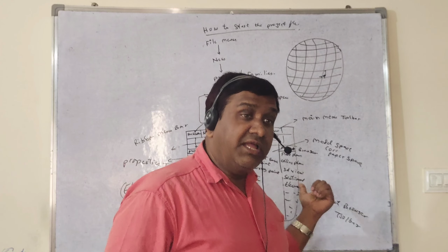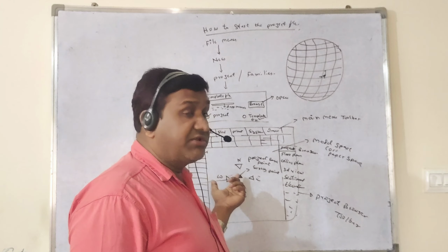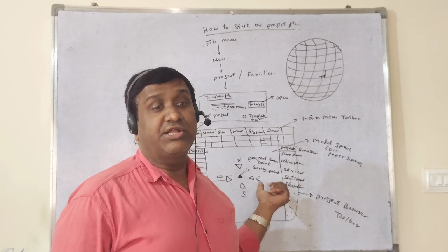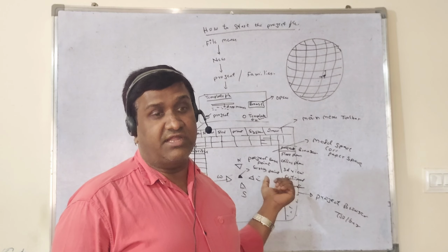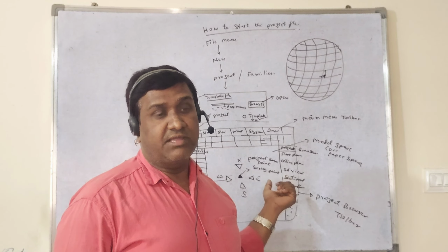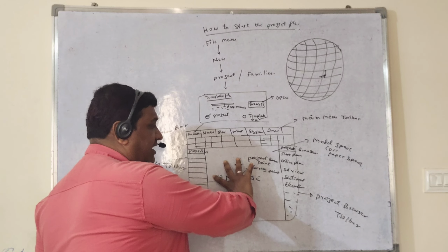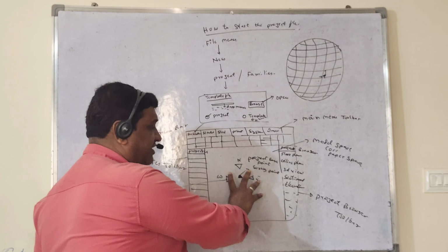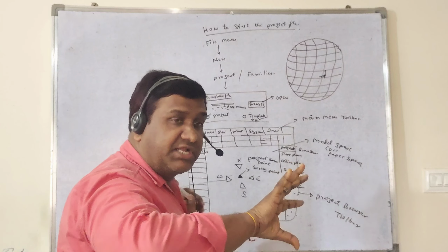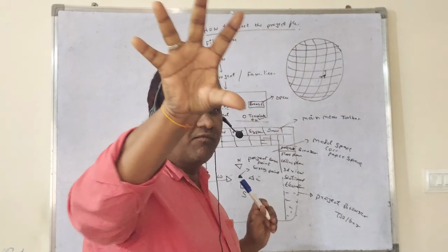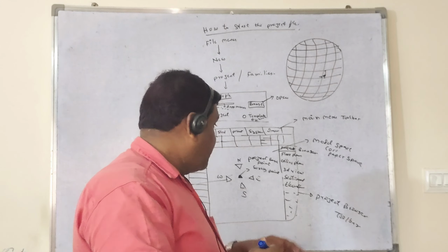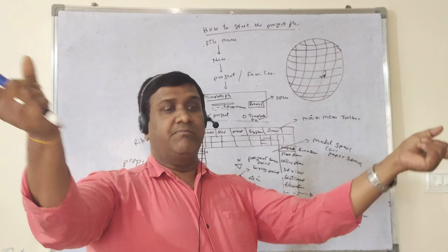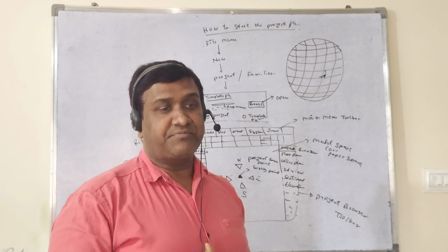Here also it is the same thing. In our project, we have to give the latitude and longitude values, that is the project coordinates, XYZ values. So when you update the XYZ values here, what will happen? Along with the north, east, south, west elevation, your project position is going to be moved from one position to another position. And your screen will become a globe. It's a globe, it's earth.